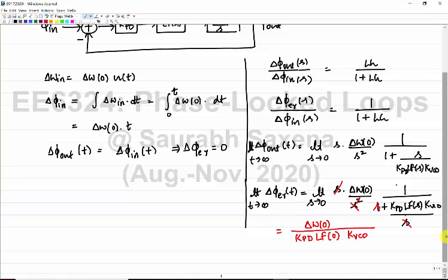We told that if we want this particular phase error to be 0, it is not 0 for all cases. If we want it to be 0, then loop filter should have infinite gain at DC. Okay, so loop filter of 0 should tend to infinity, and then only we can have phase error as 0. It will not become immediately 0, it will take some time. Okay, how much time? It depends on the loop filter. Is that okay? Okay. Any other question?